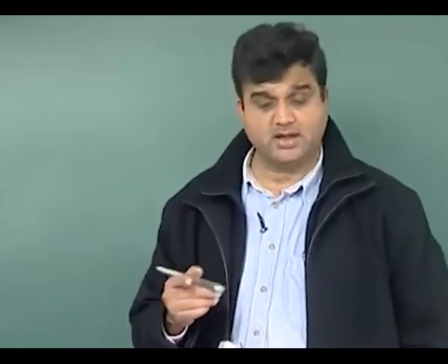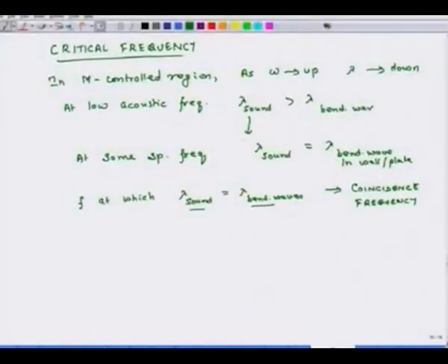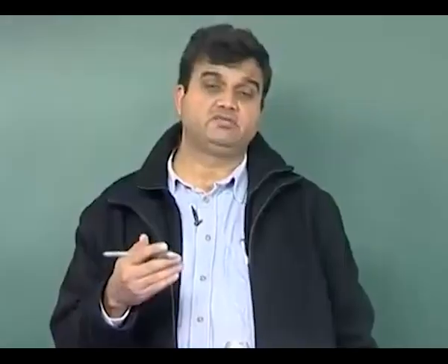So, what I am trying to emphasize is that at the coincidence frequency, the incident sound wave starts reinforcing the bending waves in the plate or the wall, which are elastic waves, and this causes a significant drop in transmission loss at those specific frequencies.